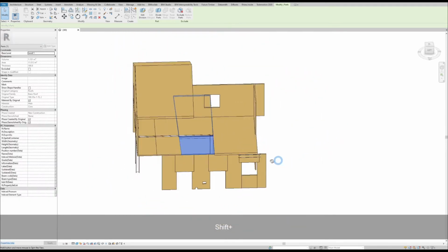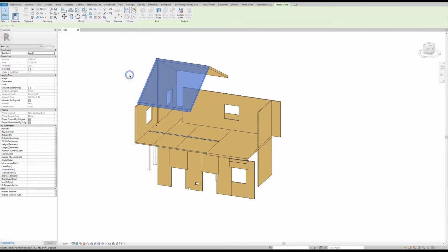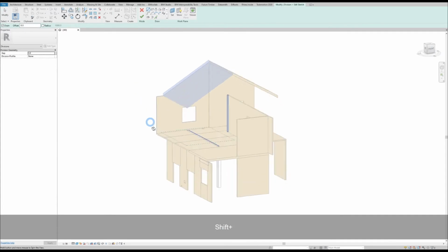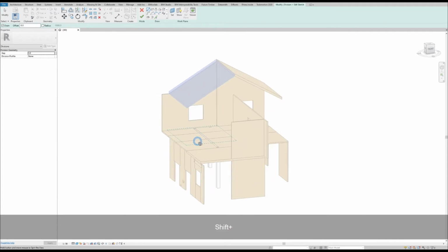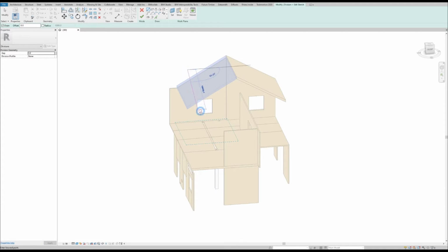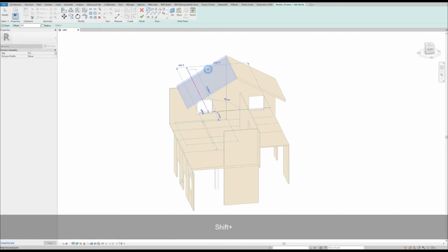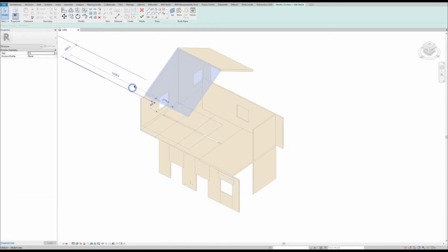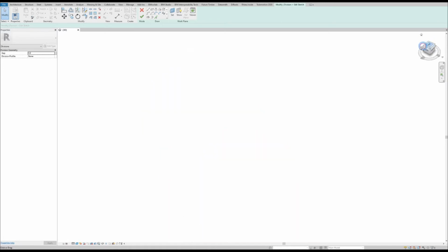So the same thing can happen on the roof. If we wanted to create some parts of this, it's the same idea. Editing the sketch, here we can understand that the plane is on this level over here. It's important for roof slabs at slopes: if we're cutting along here, the cut is not going to be as we would like it to be.